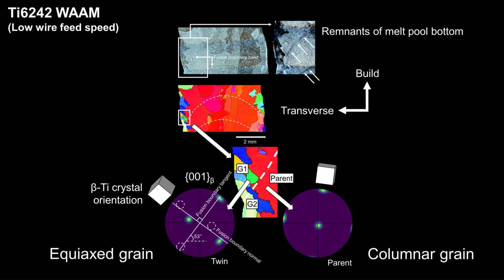We can also see that the crystal 001 direction, in which the dendrites solidify, is approximately perpendicular to this boundary, tilted slightly towards the heat source travel direction, which would match the maximum thermal gradient. So, this would indicate that the curved outer edge of the melt pool, where the maximum thermal gradient tilts far away from the vertical alignment of the interior columnar grains, has generated dendrite twins that have grown into equiaxed grains in this outer refined layer.